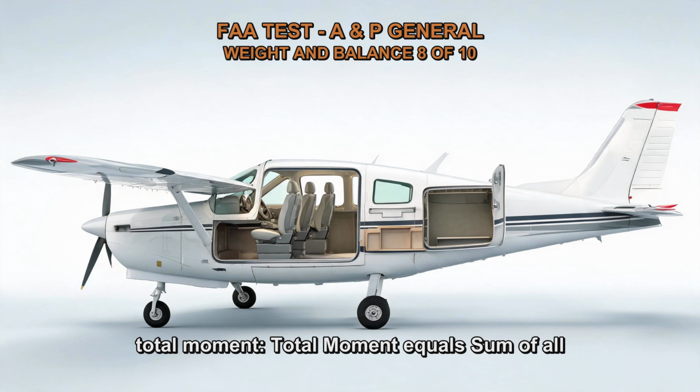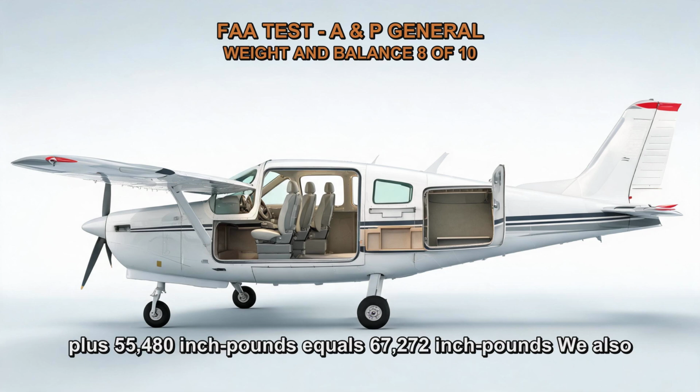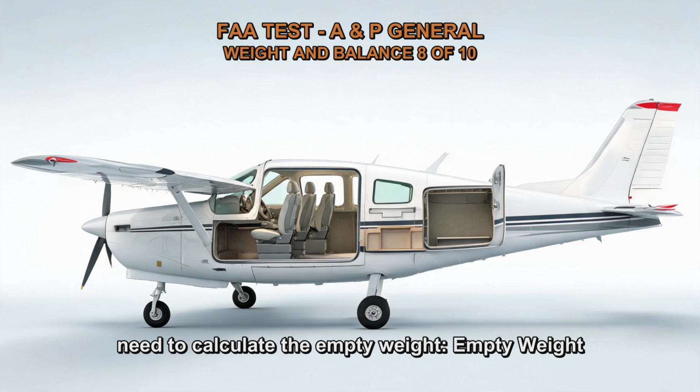Now, let's calculate the total moment. Total moment equals the sum of all the moments: 11,968 inch-pounds minus 176 inch-pounds plus 55,480 inch-pounds equals 67,272 inch-pounds. We also need to calculate the empty weight.